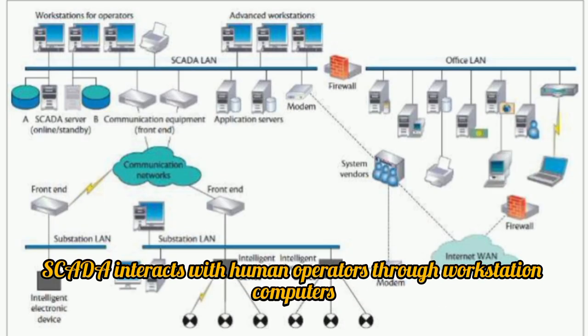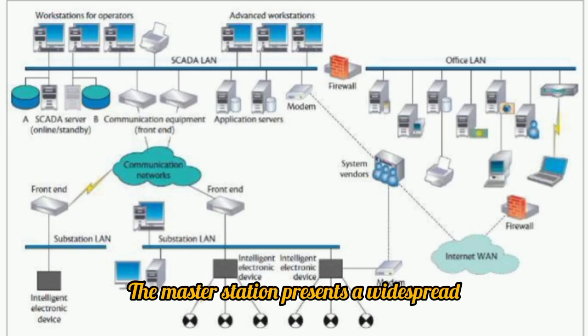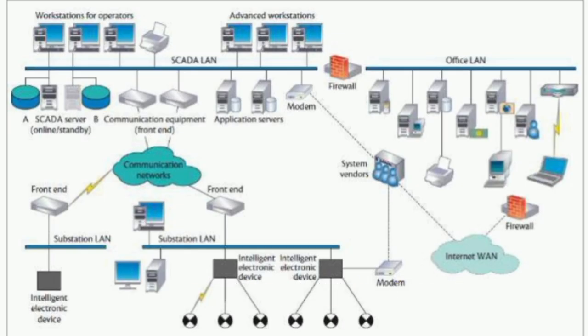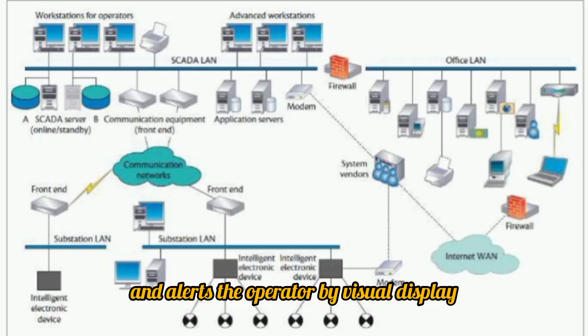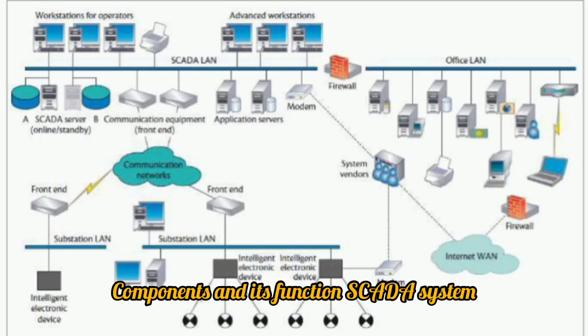Data presentation. SCADA interacts with human operators through workstation computers that deploy the human-machine interface, HMI. The master station presents a widespread view of the whole system and alerts the operator by visual display or alarm sound. Components and their function.